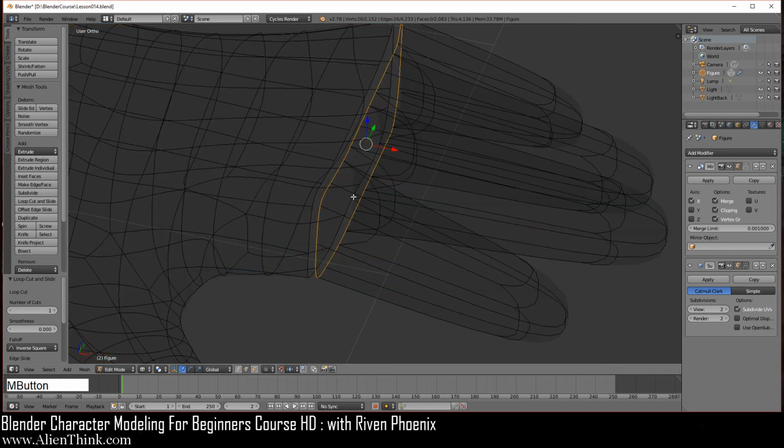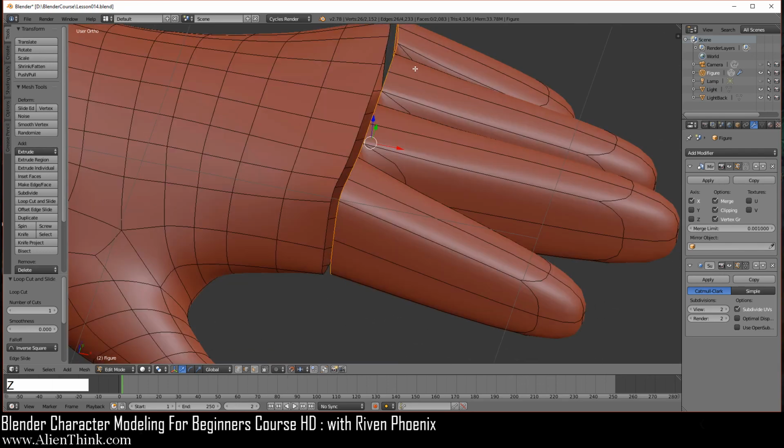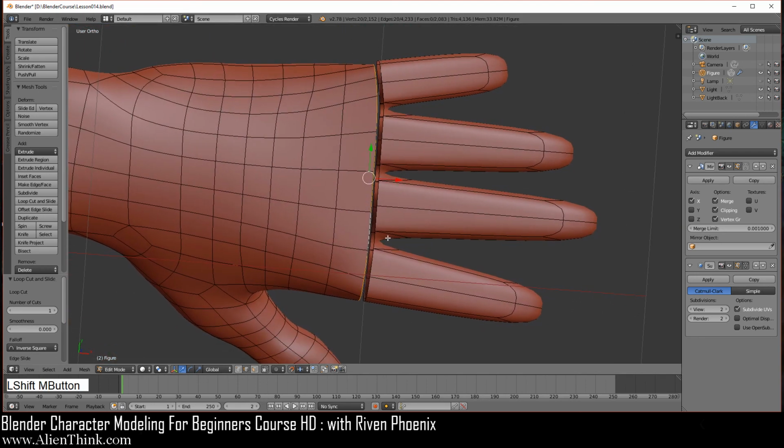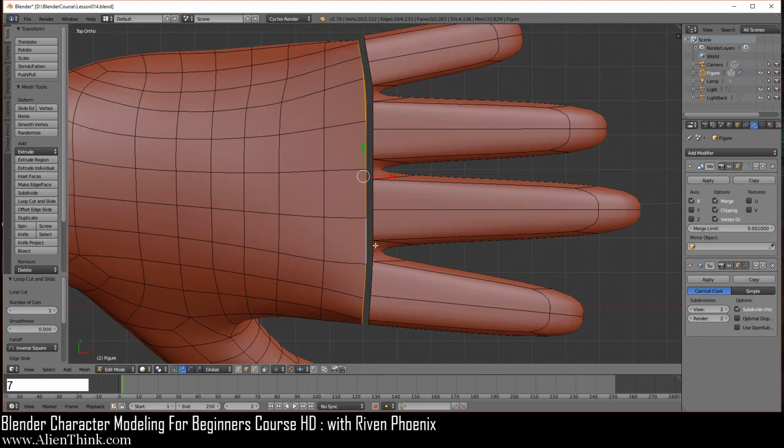Same thing, if you press Z, you can see that this is what we selected. Now look over here, it says edges, we have 26 edges. Now if I do Alt and click on this one, you can see that we have 20 edges. So this is something that we've done before, right, how to connect this. So just go into the top view over here.